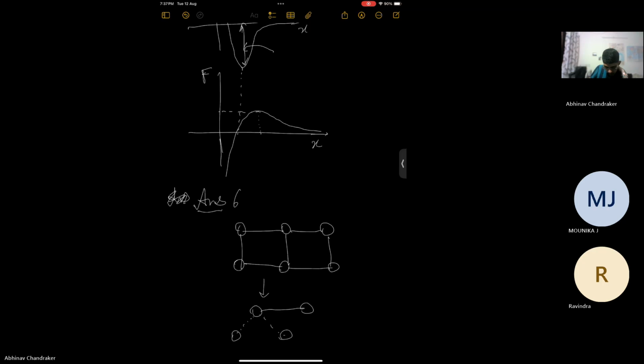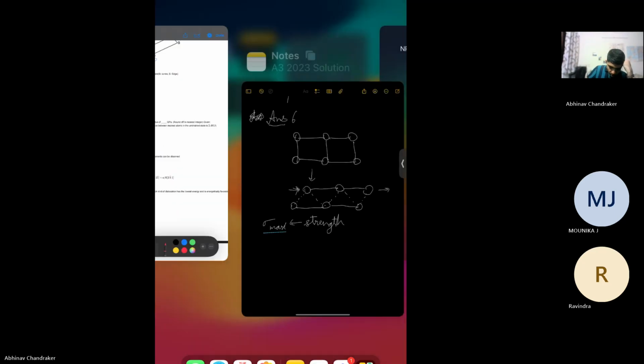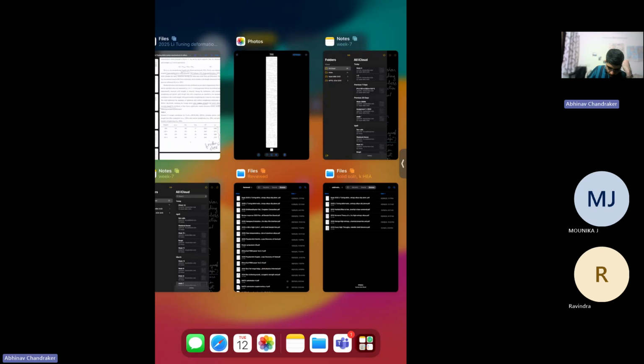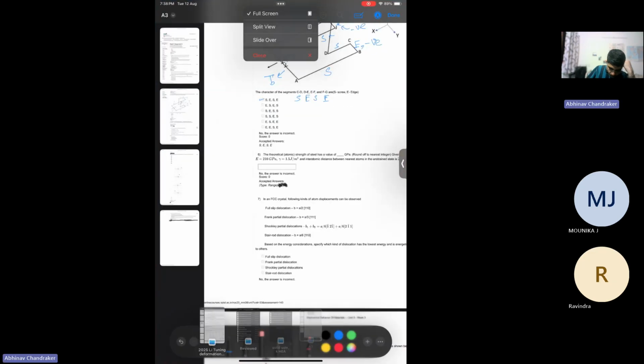This will form. As it moves in this direction, this will have a stress associated with moving, and this sigma stress required to move it, sigma max, will be the strength of the material, because if you supply a stress more than that, then the material will deform, and this has been already derived.